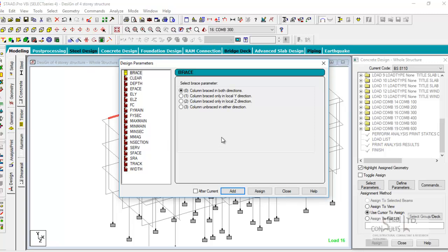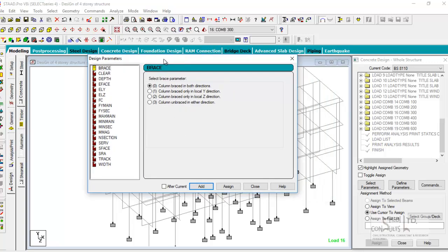Defining a structural entity. Information such as cover to reinforcement, trial sizes of reinforcement, sizes of shear reinforcement, sizes of flexural reinforcement, and so on. The characteristic material strength of steel, characteristic material of concrete. These are the crucial engineering technical information that will be specified in this design parameter, which STAAD will use inherently to design your structure after analyzing the structure to reveal the internal stresses, or the internal moments, shear forces, and so on.